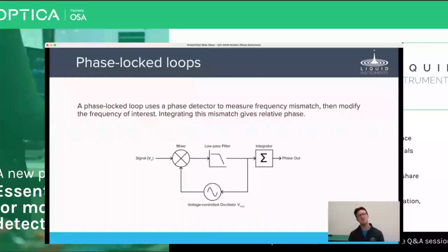So this is nice because it means that you have an oscillator here from which you can directly read out the frequency of the signal that you're inputting to the system. And if you take all those little frequency deltas, the way that it has to move in order to chase that input signal, if you take all of those and integrate it, add it all up, then you get your measurement of phase. So you can see here, our phase lock loop is this core loop, but if you take this kind of error path, this output from the single phase lock-in amplifier, this phase detector, you integrate it out, that gives you the phase of the input signal relative to the internal oscillator of your device.